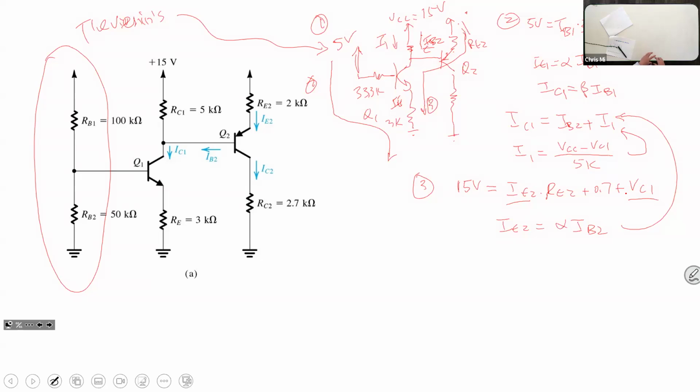You see, we have purely approximation models, like linear models, 0.7 drop and so on. But then we have physics models, and then often you go to VLSI and logic design, logic gates design and so on. It's even further simplified. They don't consider the voltage drop anymore. So when it's on, it's 0. When it's off, it's 5. Actually, it's not, right? Because we know there's 0.2 volts drop across the transistor. So it will actually be 4.8 instead of 5, right?